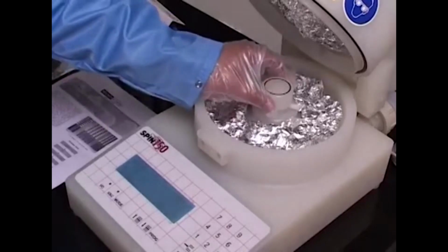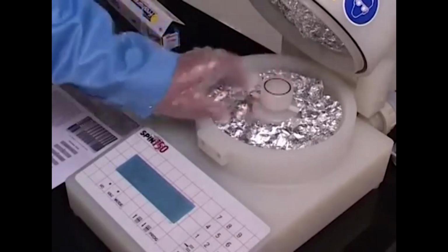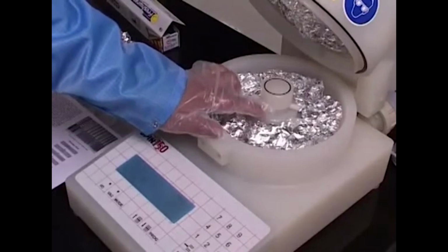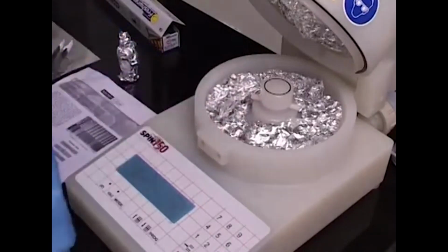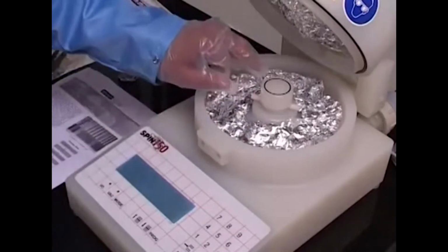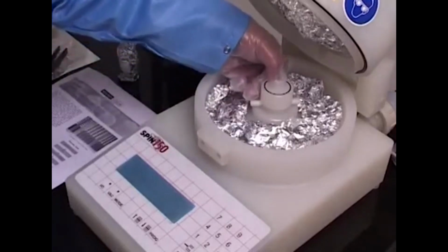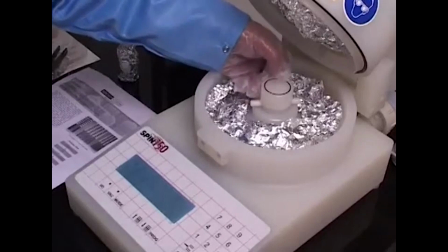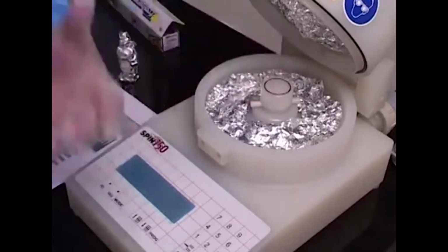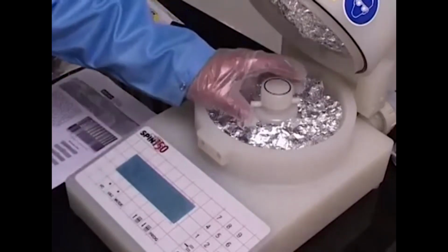The purpose of these grooves is that there is a vacuum track immediately below this which is connected to a vacuum pump underneath this whole system, and the vacuum propagates all the way up through this small center hole here and then also propagates along these grooves and holds the wafer on the top of this surface.